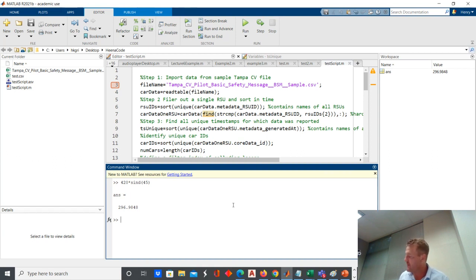So what I'm actually going to do to make this a little bit easier, rather than write down those numerical values, remember we talked about the importance of actually not rounding intermediate results in order to not affect our results. So I'm actually going to store the y components and the x components as actual variables, and then I will add those at the end. So I'll call the y component of f2 420 times sind of 45, and I'll store that. I'll call the x component of f2 minus 420 times the cosd of 45.